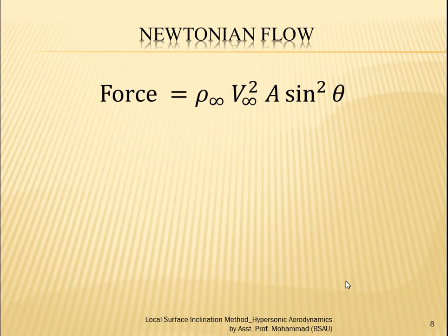Writing the force again, the force is rho V infinity squared A sin squared theta, by joining those two terms together. So force is basically proportional to sin squared theta, and that's what Newton gave. So it was the sine squared law. That is the very famous sine squared law, because force is proportional to the sine squared of the angle of inclination.